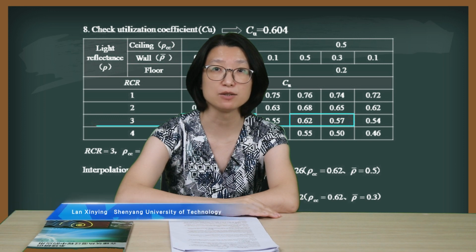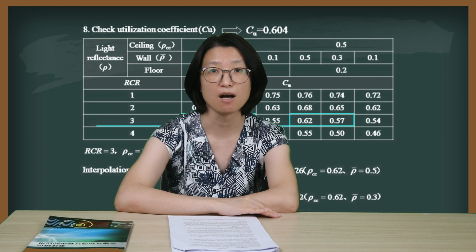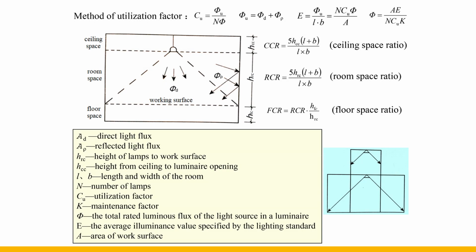After analyzing the visual characteristics of the design object, selecting the appropriate lighting method, determining the required luminance and quality indicators, and selecting the light source and lamps, the lighting calculation stage is entered, and the required single light source power is obtained, or we check whether the illuminance meets the standard according to the predetermined single lamp power. Lighting calculation commonly uses the utilization coefficient method.